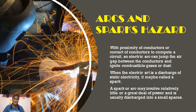Then we will move on to the arcs and sparks hazard. With proximity of conductors or contact of conductors to complete a circuit, an electric arc can jump the air gap between the conductors and ignite combustible gases or dust. When the electric arc is a discharge of static electricity, it may be called a spark. A spark or arc may involve relatively little or a great deal of power and is usually discharged into small spaces.